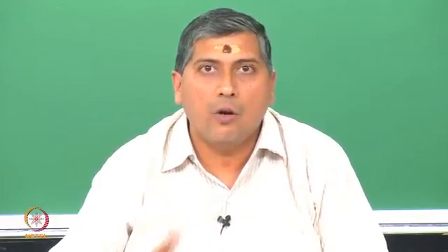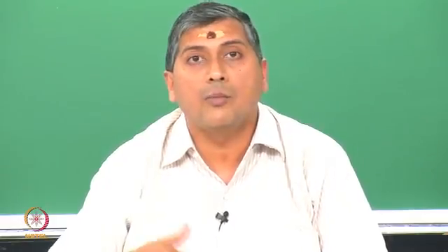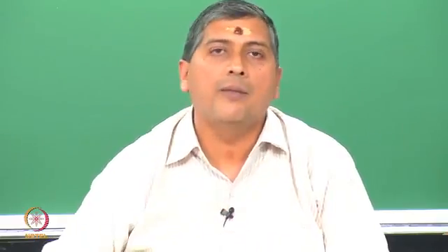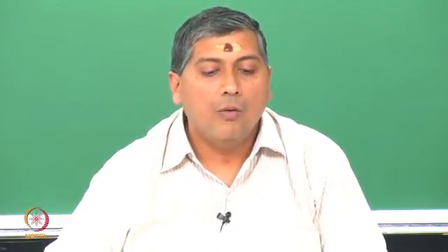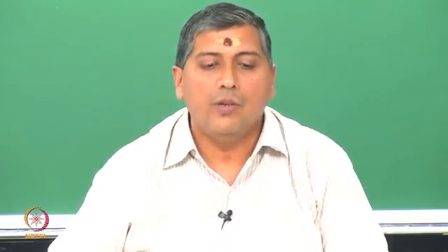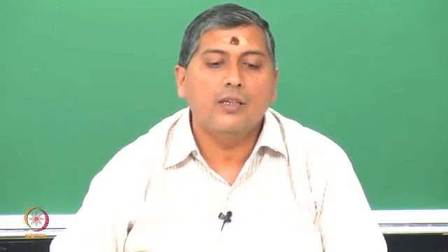So there is no particular algorithm that one can recommend. From a computational viewpoint, the Fourier transform algorithm is much faster, but it assumes the signal to be periodic. The convolution algorithm is computationally more intensive, but it does not make any assumptions on periodicity outside the interval. What we shall do in the next lecture is study scalograms, which are computed from the CWT. This is an important precursor to the computation and discussion of the scalogram, and here are a few references.